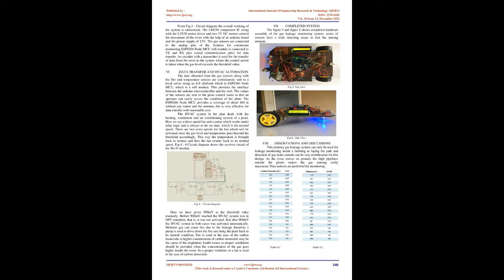The operating voltage of the MQ136 gas sensor is 5V and its sensing material is tin oxide. Its electrode material and electrode lining material are gold and platinum respectively, thus making it one of the expensive MQ series sensors. The MQ2 gas sensor is used specifically for the detection of gases like methane, butane, LPG, smoke, etc. Its digital pin helps us to use the sensor even without a microcontroller.